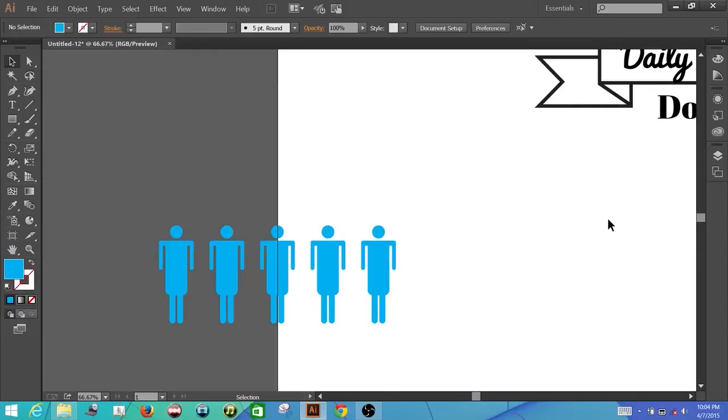Let's go ahead and create our shower head. Come over here to your toolbox to the rectangle tool. Click, hold, release mouse. Pick up your ellipse tool. Come back over here to your workspace. Click, hold down Shift and Alt key, drag out a circle about this big. Release mouse, then keyboard. Go ahead, pick up selection tool and deselect.